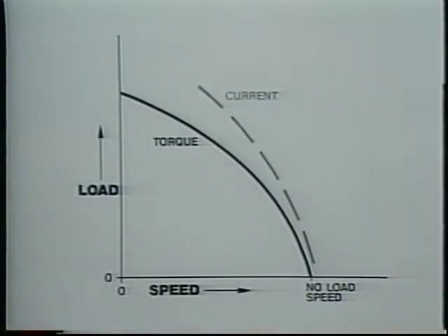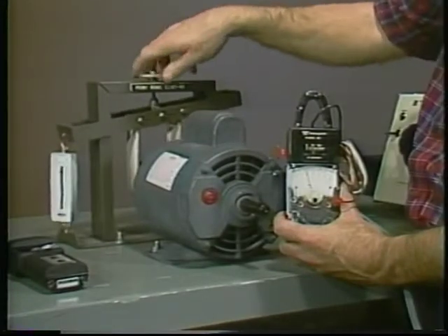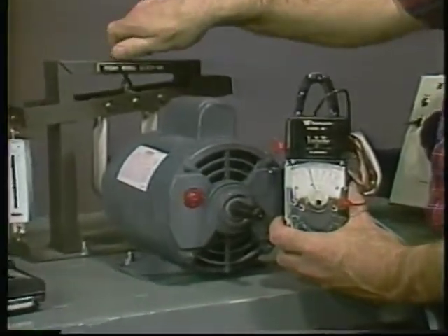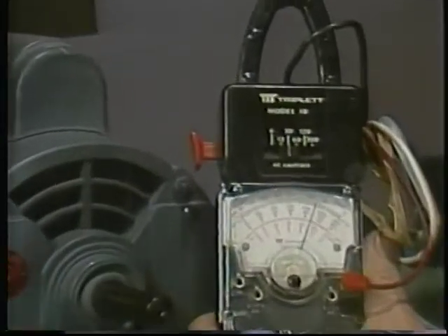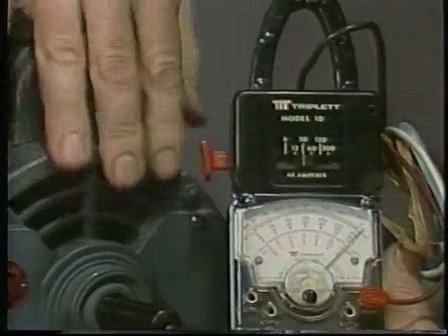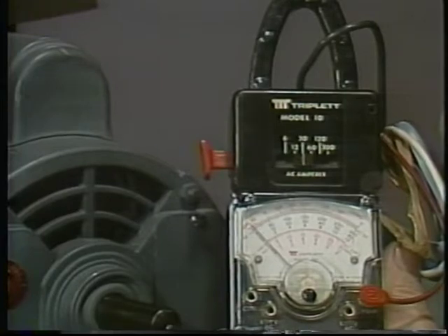As the motor approaches stall, current rises sharply because the motor is trying to provide the required torque. When operating under heavy loads at low speeds, motors will usually trip their overload breakers quickly. Even so, running a motor under high current conditions will soon burn it out.